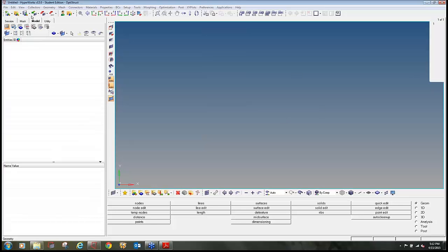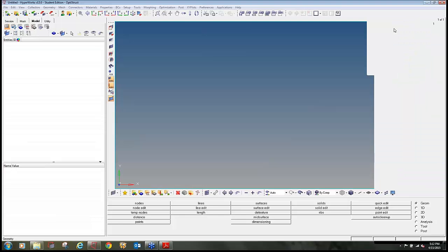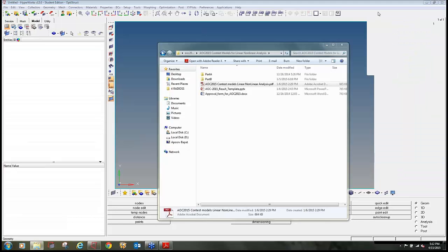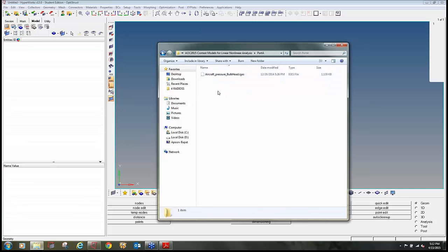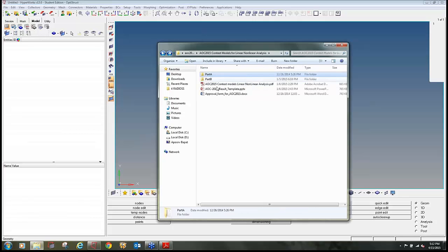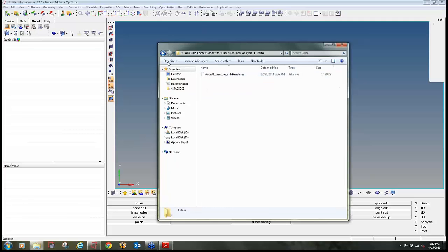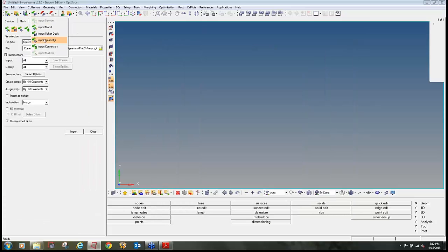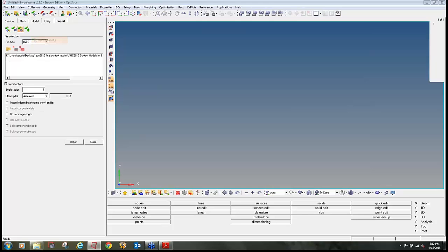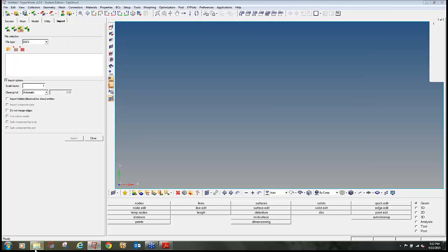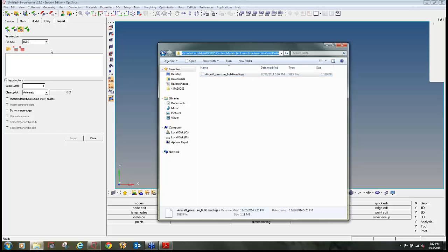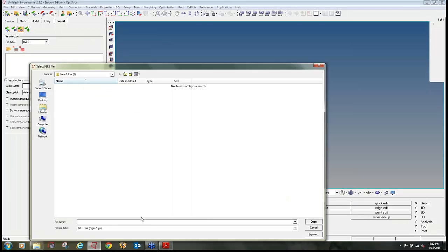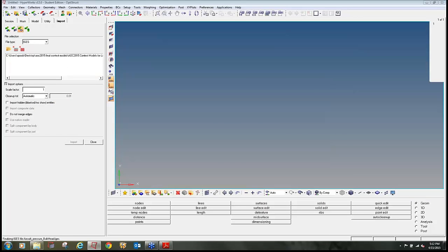Now I will import the model. As I can see, the models provided to me are in IGS format. I think you have downloaded the zip folder which I have provided to you. In that there is a part A and part B, in IGS format. So I will import this model. Go to the import icon, geometry, select the file, copy, open, paste, and click on import.